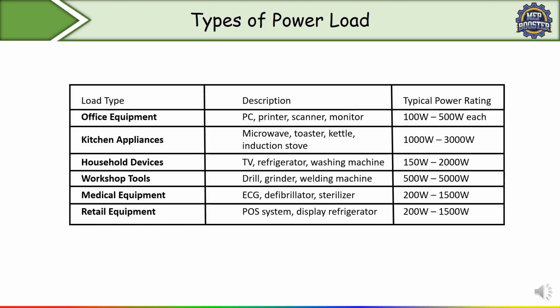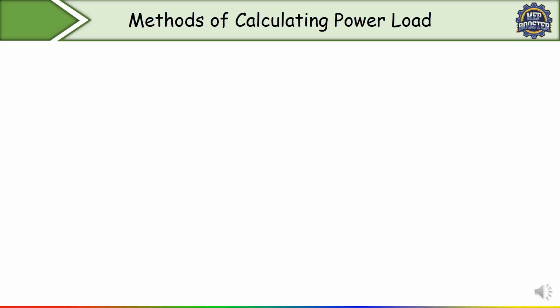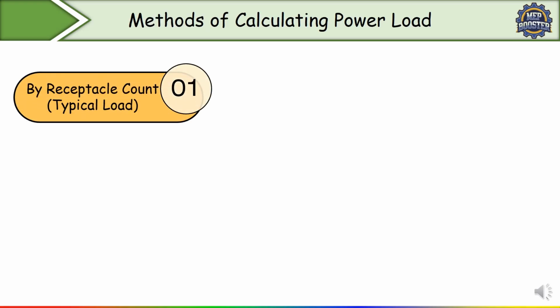Now the question is how to calculate the power load. I will show you the methods of calculating power load. The first is by receptacle counts. NEC or IS code allow us to estimate based on the number of outlets and type of room.